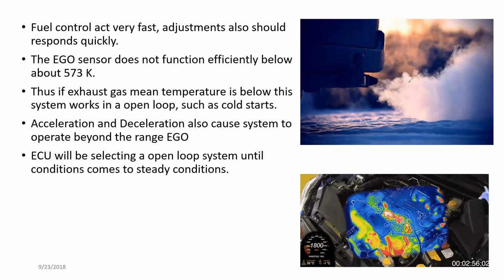As I told you earlier, there are some instances where the engine management system works as an open loop control system. The main instance is when the engine is started in the early morning, like a cold start. During the cold start, the oxygen sensor is not up to the temperature to deliver correct readings.